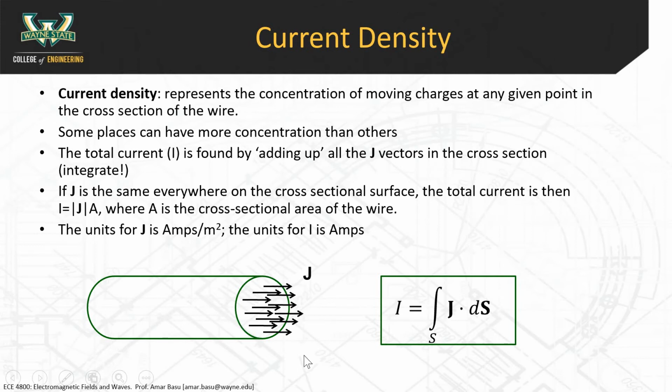Another example is if you have a wire of differing cross section. In electronic circuits, what often happens is you may have a big wide trace, and then in some parts of the printed circuit board, because everything's super dense, you have to make that trace a little bit smaller to connect to one of your electronic components.